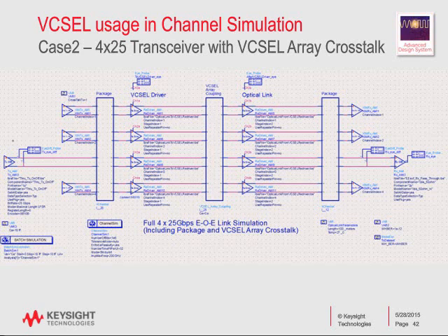Well, what I've done here is I've split the optical link into two. I put the VCSEL driver as one stage, and the rest of the optical link from the VCSEL onwards as another. And you can see that I put a block in the middle, which is a fairly simple model inside. It's looking very complicated, but it's just cross-connected, very low-level capacitance. And I'm allowing the crosstalk to occur between the VCSEL driver and the VCSEL itself. So again, it's in the electrical domain.